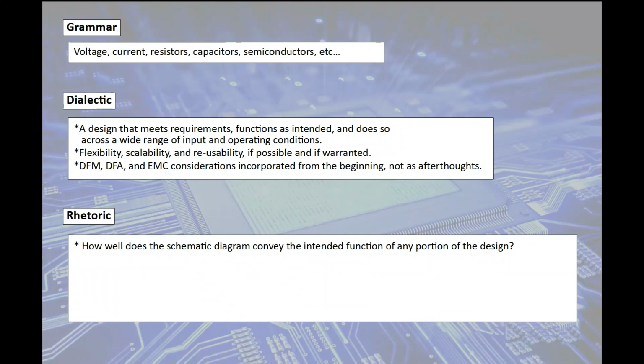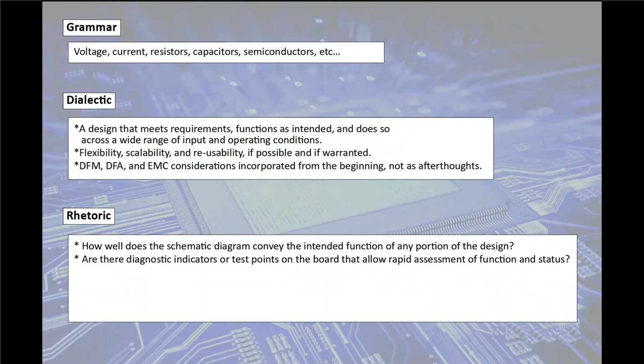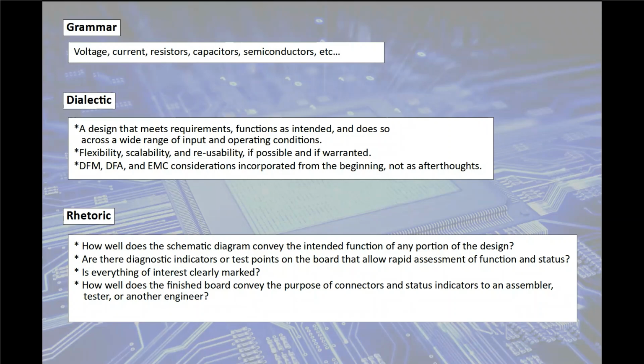And now the rhetoric. How well does the schematic diagram convey the intended function of any portion of the design? Are there diagnostic indicators or test points on the board that allow rapid assessment of function and status? Is everything of interest clearly marked? How well does the finished board convey the purpose of the connectors and status indicators to an assembler, to a tester, or to another engineer? And do the ergonomics make assembly or use intuitive?